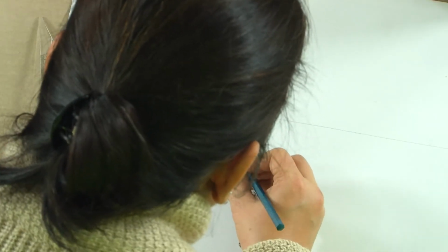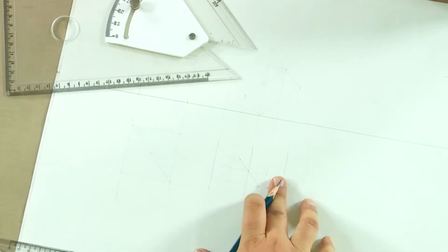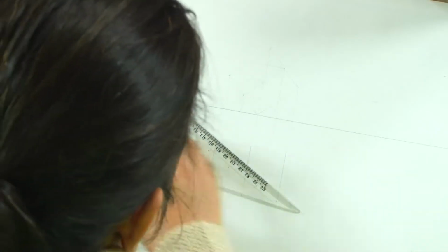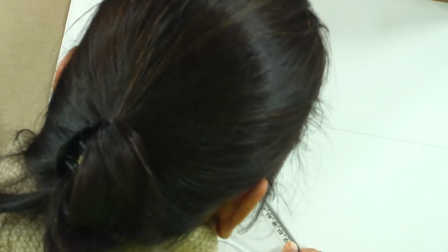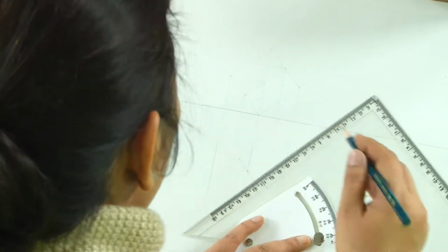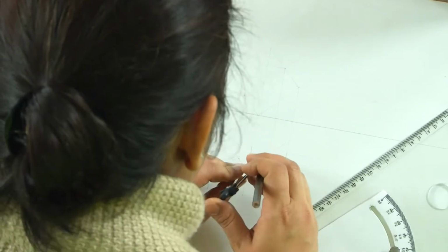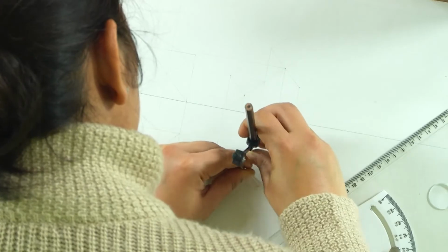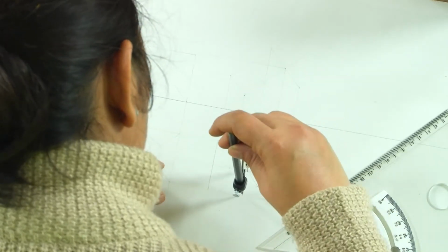So what we get here is this, and now we will rotate this entire cube about this axis. Since if this was the axis and there was this perpendicular, let us set our set square to match this axis and draw perpendiculars and trace all the points onto these lines.